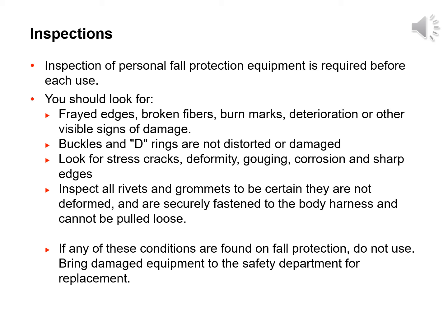Snap hooks and eyes should not be distorted or bent. Inspect them for cracks, sharp edges, gouges or corrosion. Check to be sure the locking mechanism is operating properly and that there is no binding of the mechanism.